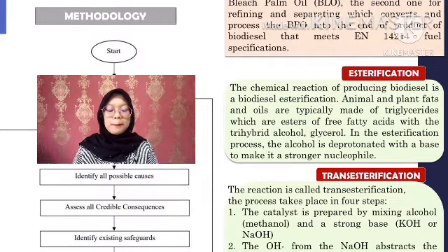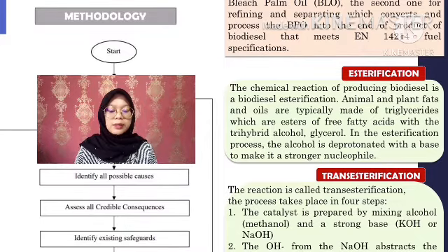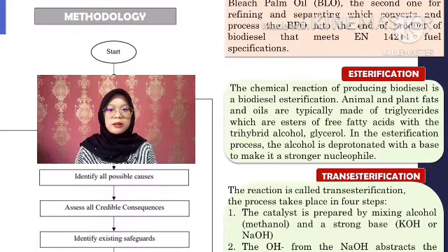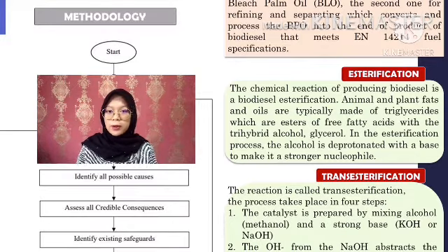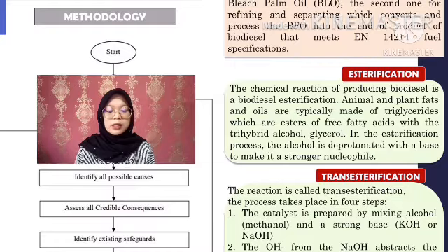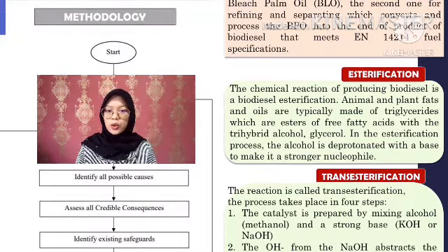Almost all biodiesel is produced from virgin vegetable oils using the base catalyst technique, as it is the most economical process for treating virgin vegetable oils, requiring only low temperatures and pressures and producing over 98% conversion yield. However, biodiesel produced from other sources or by other methods may require acid catalyst, which is much slower.